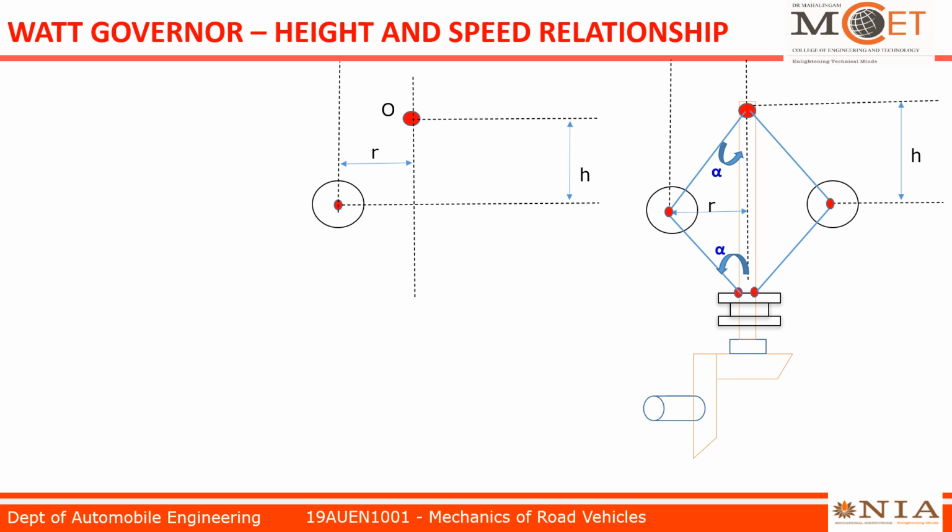Since this governor is rotating and also comes under centrifugal governor, it makes centrifugal force. The centrifugal force will act away from the spindle, that is in the outward direction from the spindle, so the centrifugal force will act on the fly ball because of rotation of spindle and governor. It will be in the left hand direction.